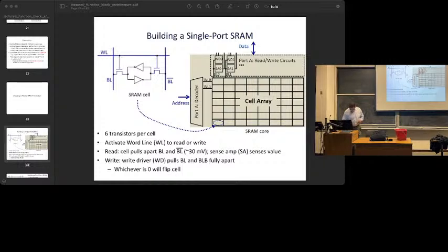So inside a RAM, there's actually all sorts of tricky, what are called self-timed circuits. Self-timed circuits just means they're like delays. A clock hits the RAM, and this pre-charge starts. So a circuit kicks in, and it detects that it's supposed to do a read. It starts pre-charging both these to VDD over 2.